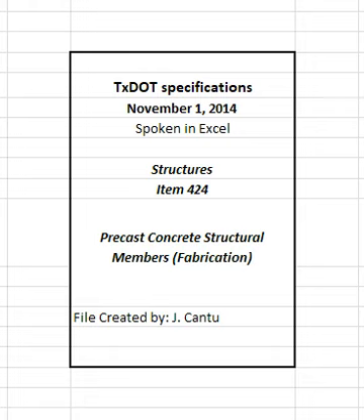6. For draped strands, the tolerance for vertical position of strands at the end of the beam may be increased to plus or minus 1/2 inch provided the tested concrete compressive strength, before release of tension into the member, is at least 5% greater than the release of tension strength shown on the plans. 7. Measured from bottom of panel. 8. 3/4 inch maximum for beams exceeding a height of 54 inches.